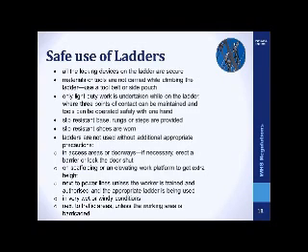For the following scenarios, and access areas or doorways, if necessary, erect a barrier or lock the door shut. On scaffolding or an elevated work platform to get extra height is never a suitable use. Next to power lines, unless the worker is trained and authorised and the appropriate ladder is being used. Must not use ladders outdoors in very wet or windy conditions, or next to traffic areas unless the working area is barricaded.